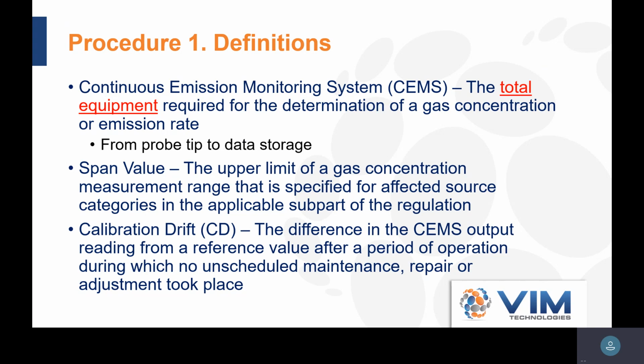One thing I wanted to mention about the CEMS is a lot of times I'll hear my clients say they have a NOx CEMS, a CO CEMS, an SO2 CEMS. Well, actually, you have one CEMS with a NOx, SO2, and O2 analyzer in it, because it's the complete system. So I was talking to a fellow today, and he said they have 90 CEMS at their facility, and I was like, whoa, how big is your facility? But he actually had 30 CEMS systems, with 90 analyzers. So it's important to distinguish that CEMS is the whole system, not just a particular analyzer.